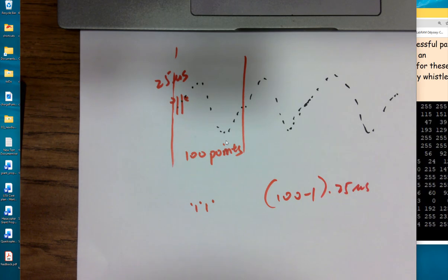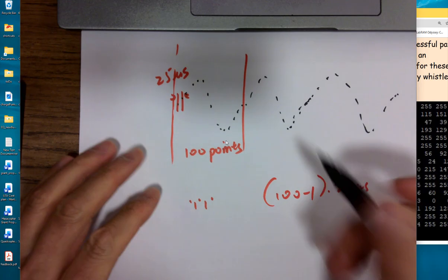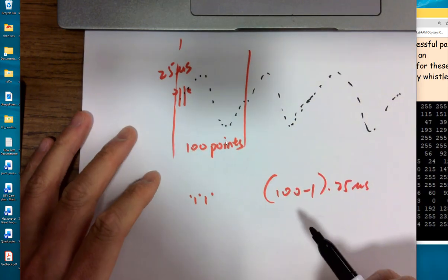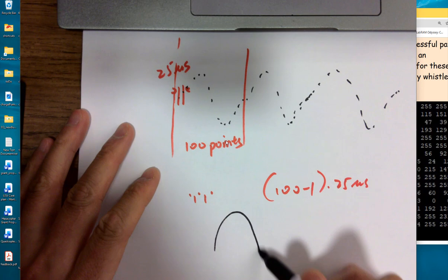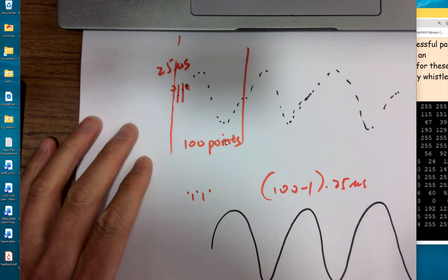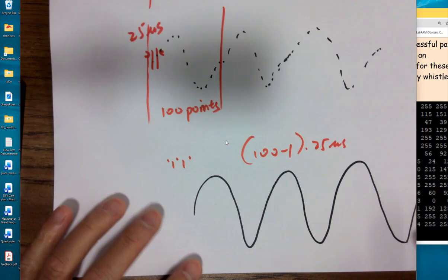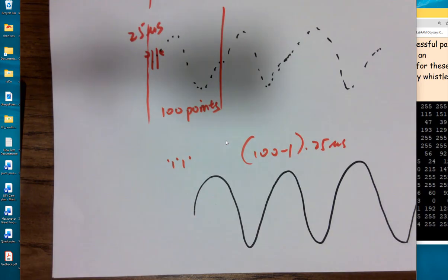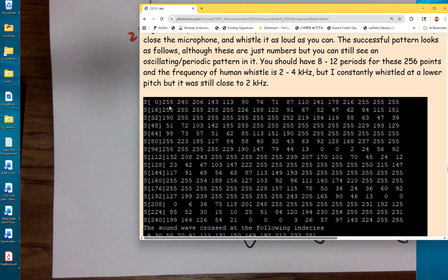So the way we measure it is in your code, right? I want to let you guys think about it first. What the ADC can do is just sample a bunch of points, maybe hundreds of points, and store the points in the buffer, right? So eventually, what you got is all the points. You print it out. These are the points the ADC sampled. So basically, just bytes, 8-bit numbers in there.